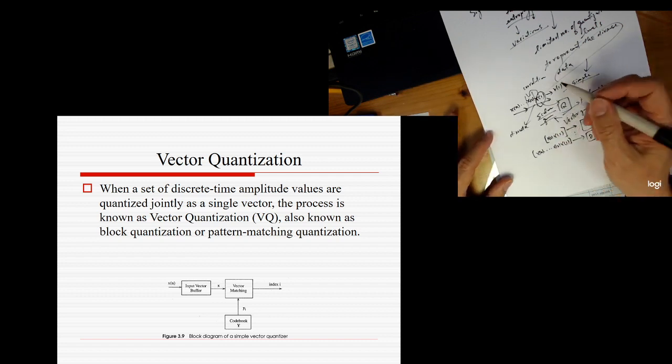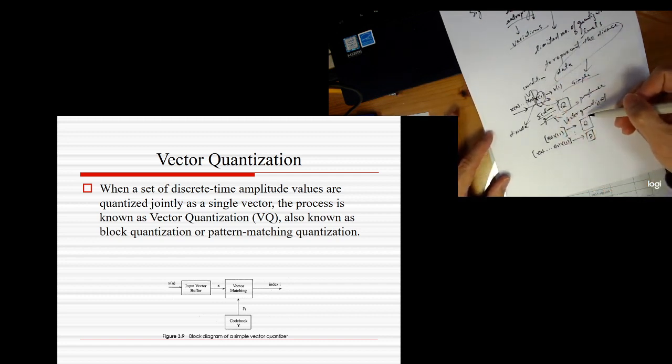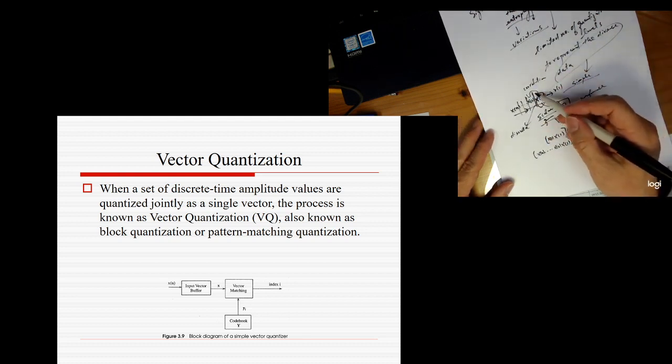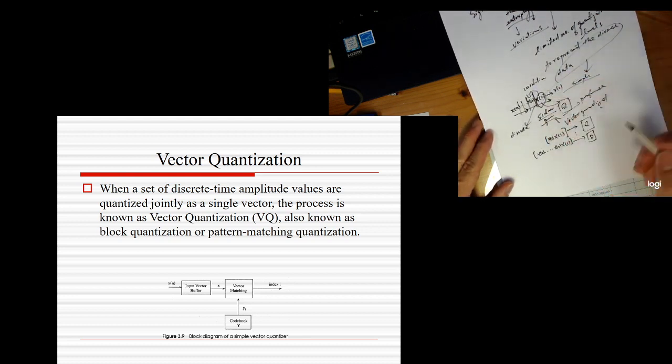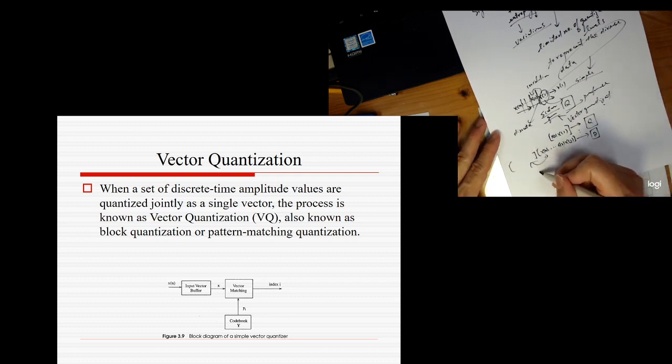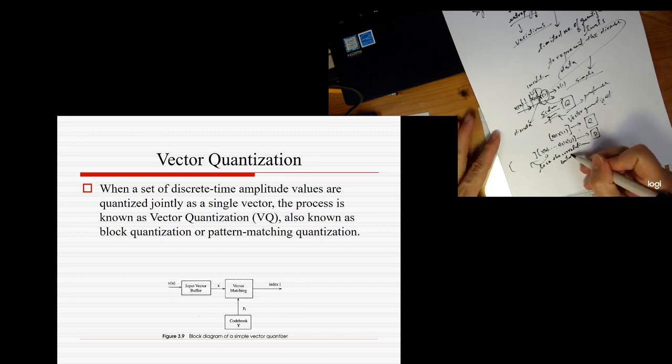However, scalar quantization performance is not as good as vector quantization, because it partitions the signal discretely. There will be loss of correlation between neighboring signals. Vector quantization considers neighboring signals together to do the quantization. However, the correlation between the vectors will be lost.